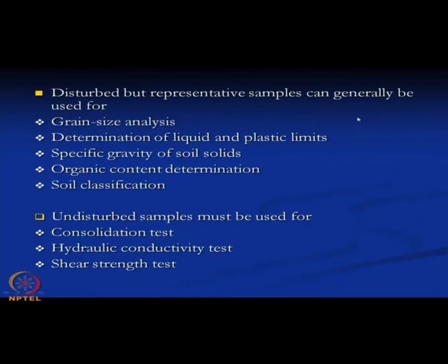Now, where will the disturbed sample be used, and where will the undisturbed sample be used? The disturbed sample will be used for grain size analysis, determination of liquid limit and plastic limit or whatever limits of the soil, specific gravity of the soil solids, organic content determination and soil classification. For the strength properties of the soil, that is the shear strength test, then the consolidation test, and the hydraulic conductivity test,